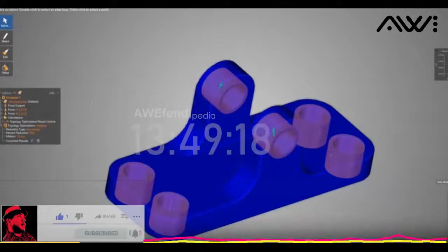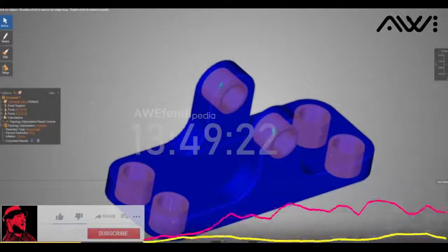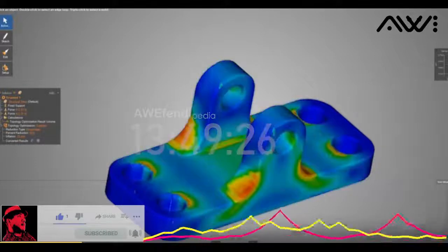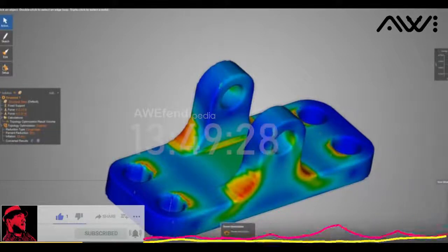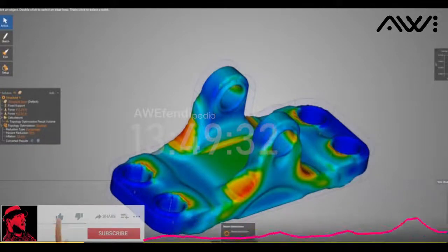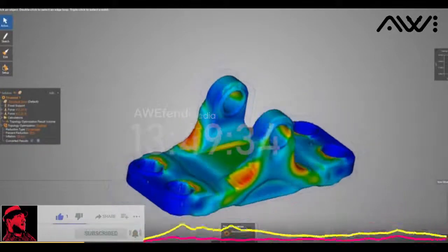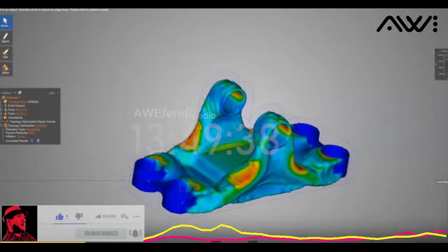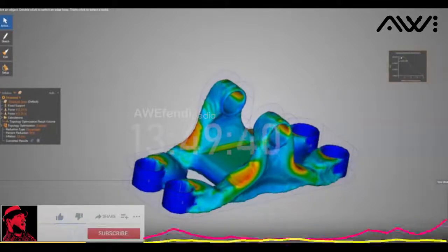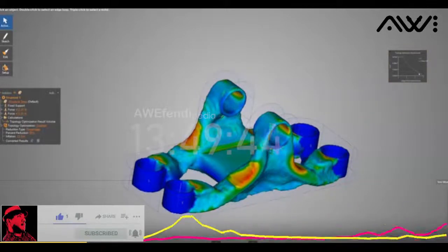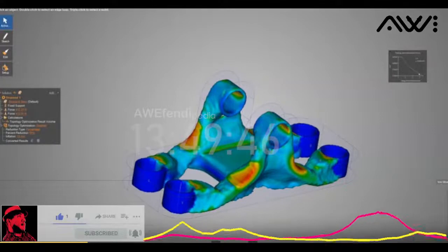There's not a lot to go with. There's no other constraints I need to add because I have my forces and support. So all I'm going to do is now hit play. Now we're going to talk about this bottom menu here. What this is actually showing, and this is all real time right now, is how quickly we're going to iterate. I actually have a time in my other example. We have these calculators on the far right, and a graph showing me where I'm going to converge to. As I get down to 0, it's going to continue and flatten out.